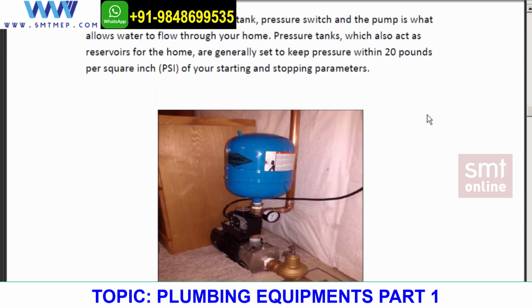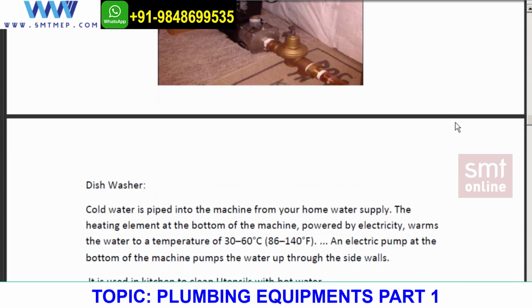We'll have a calculation, we'll see this later on. Right now, just see how and why the pressure tank is being placed. It is a very good option because boosters alone are expensive machines, so they need quick maintenance and all this. If there is a sudden breakdown, then there will be no water. To avoid all this, we have this kind of tank there, a pressure tank.